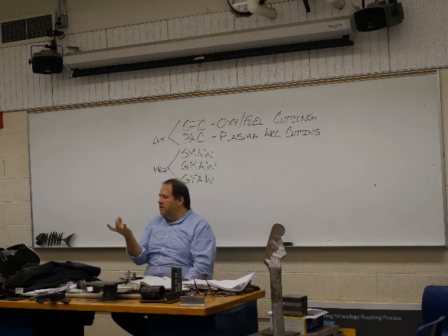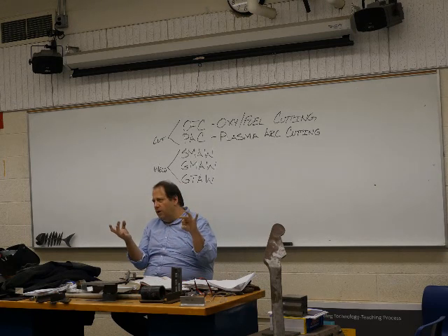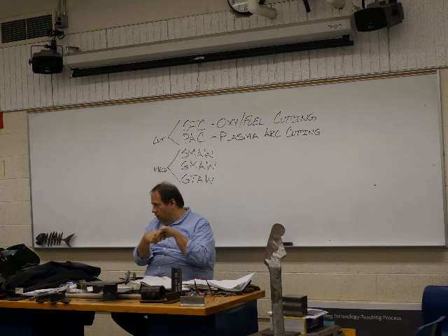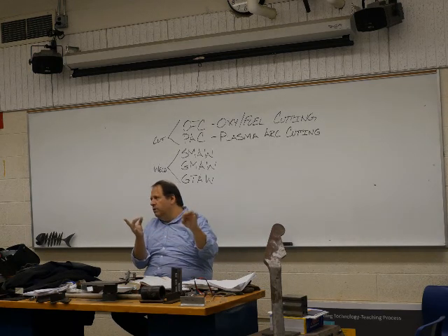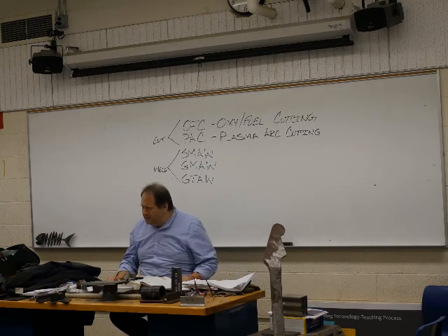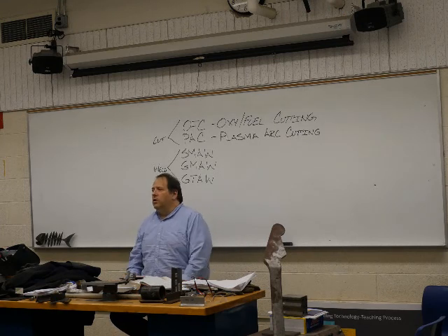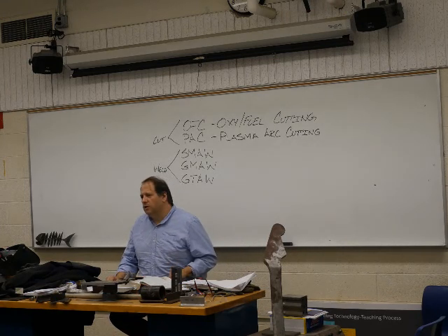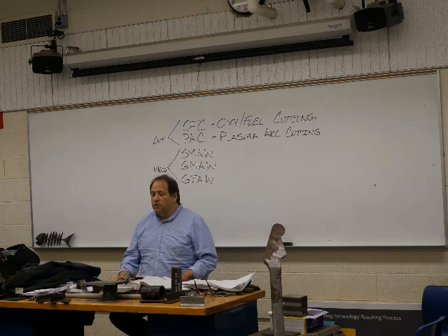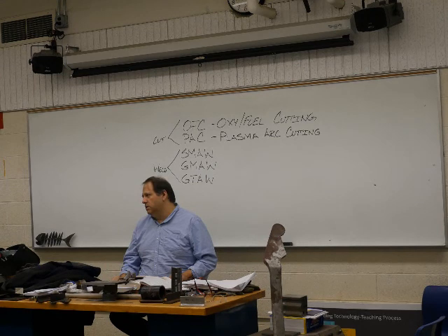Same kind of principle as taking, say, a water line of a certain thickness, and then putting a smaller tube on the end. You're going to get pressure as it goes through that smaller hole. You get flow here, and then it'll build pressure trying to get through that smaller hole, and it'll spray out from it. Kind of the same thing happens. Only what we're going to do is get a really supercharged, hot arc coming out of the torch of the plasma cutter. So we get an arc that comes out at about 20,000 degrees.